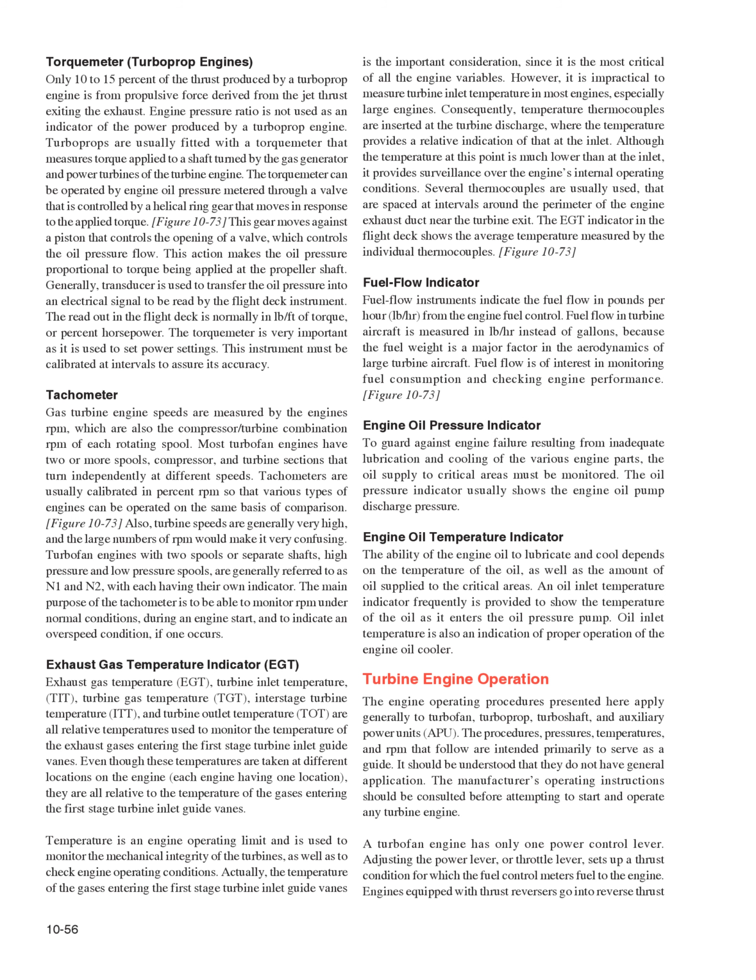Turbine engine operation. The engine operating procedures presented here apply generally to turbofan, turboprop, turboshaft, and auxiliary power units, APU. The procedures, pressures, temperatures, and RPM that follow are intended primarily to serve as a guide. It should be understood that they do not have general application. The manufacturer's operating instructions should be consulted before attempting to start and operate any turbine engine.